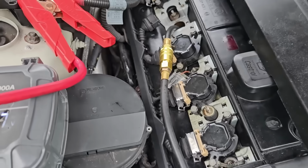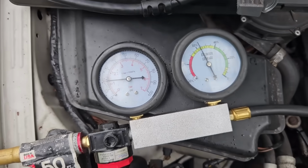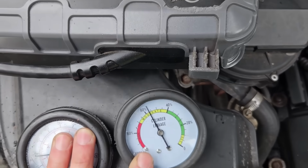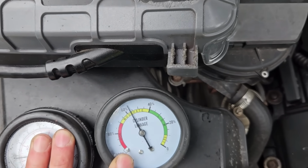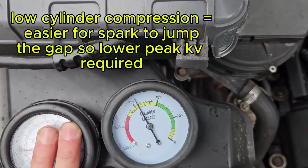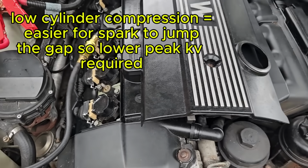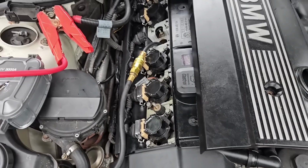Alright, got the engine at top dead center. We're doing the leak down test. Cylinder 4 showing 65-ish, or my bad, 55-ish percent. If we listen to the tailpipe, we can hear air hissing out of there, so we have a leaking exhaust valve.